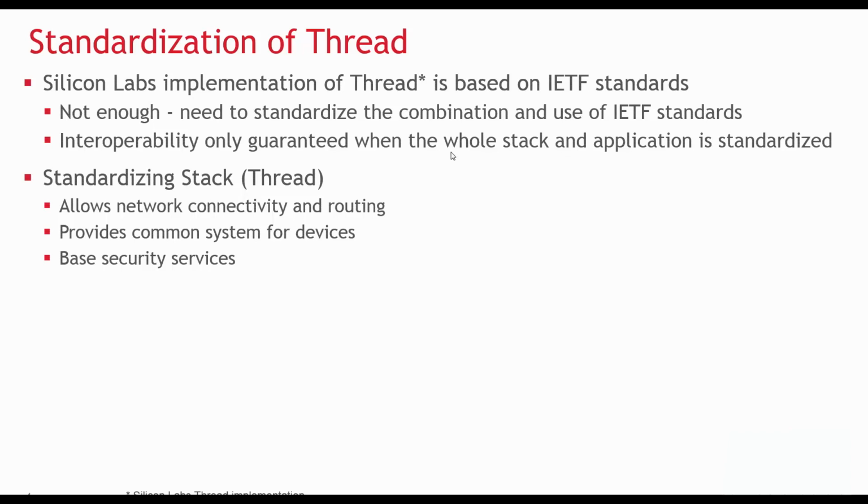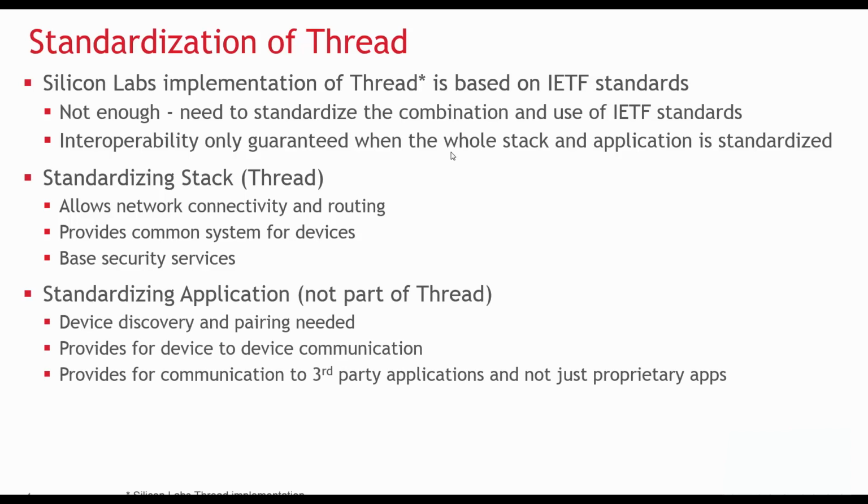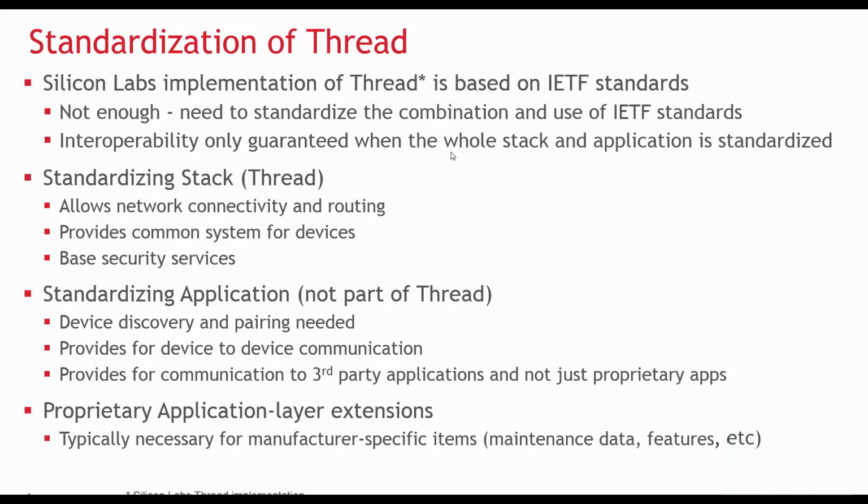While the IETF standards-based stack elements can be verified by the aforementioned UL testing, true interoperability between Thread-based devices requires agreement about which application layer to use. Application layer behaviors that need to be agreed upon and tested for interoperability include device and service discovery, pairing of complementary devices such as a switch and light, specific command and response formats and behaviors for various kinds of devices, and required functionality among similar devices from different vendors. Any vendor-specific enhancements to a standard application protocol will need to be discoverable by some standard process and added in a way that doesn't compromise standard functionality.